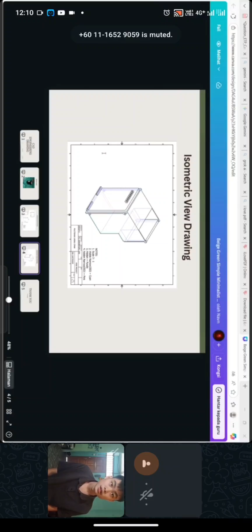Drawing organization is also important. We arranged all elements neatly, avoided overcrowding, and ensured the spacing between dimensions follows ISO standard. For plotting, we chose the correct paper size A3, appropriate line weight, suitable scale, ISO drawing border, and title block. This ensures the drawing would be printed professionally.